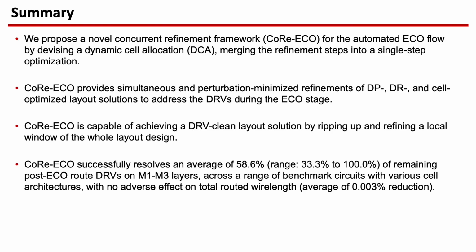In summary, we proposed a novel concurrent refinement framework for the automated ECO flow. Our framework provides simultaneous and perturbation-minimized refinements of detailed placement, detailed routing, and cell-optimized layout solutions by lifting up and refining a local window to address the DRVs during the ECO stage. And we have demonstrated that our framework successfully resolved the remaining DRVs across a range of benchmark circuits with no adverse effect on the